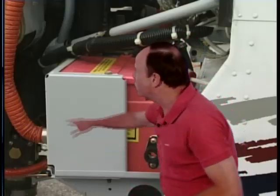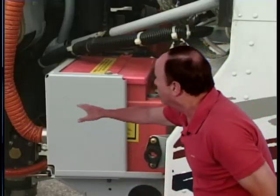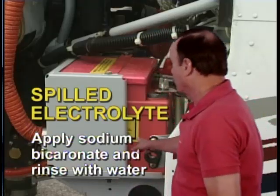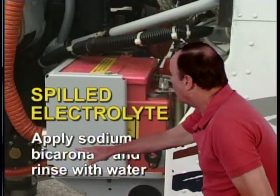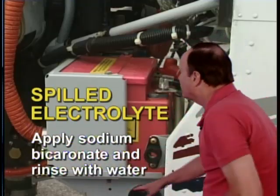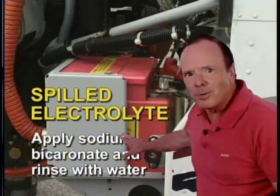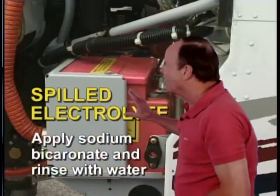And what you want to do is neutralize it with an alkali. The electrolyte is very acid. You want to neutralize it with an alkali, so you'd use something like sodium bicarbonate, because that's an alkali. So you'd apply sodium bicarbonate, and then of course you wouldn't want to leave that lying around the aircraft, so then you'd rinse it with water. The best thing is, don't spill the electrolyte. The owner will not like it.